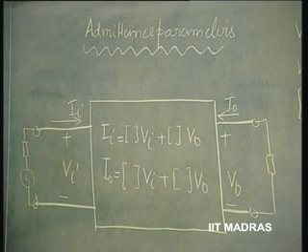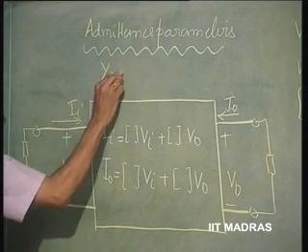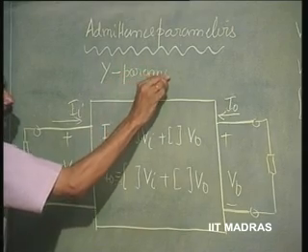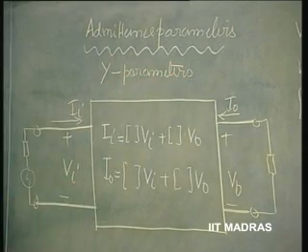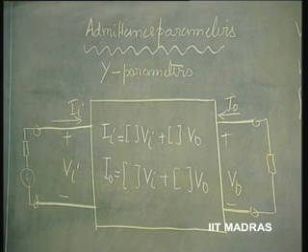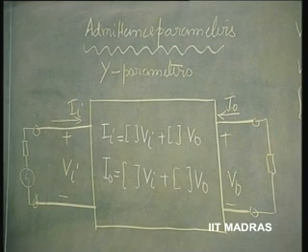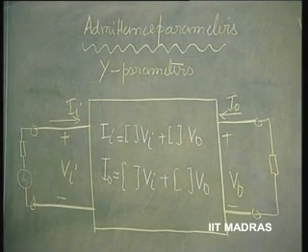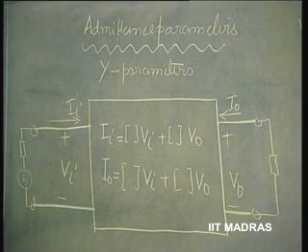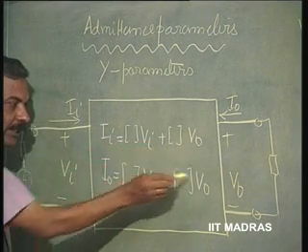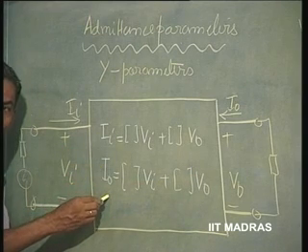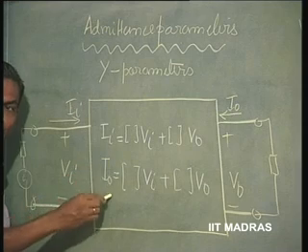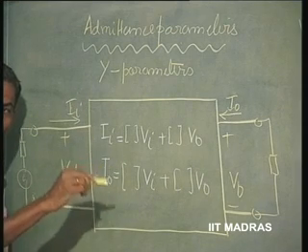We were exposed to Z parameters. Now, let us see the dual of that, Y parameters or admittance parameters. These are called admittance parameters or Y parameters. Earlier, they were called impedance parameters or Z parameters. Let us see. Again, it is very simple to formulate now. The independent variables are Vi and V0 as against II and I0 earlier. So, Vi and V0 are independent variables and II and I0 are dependent variables. What it means is II and I0 are expressed in terms of Vi and V0.